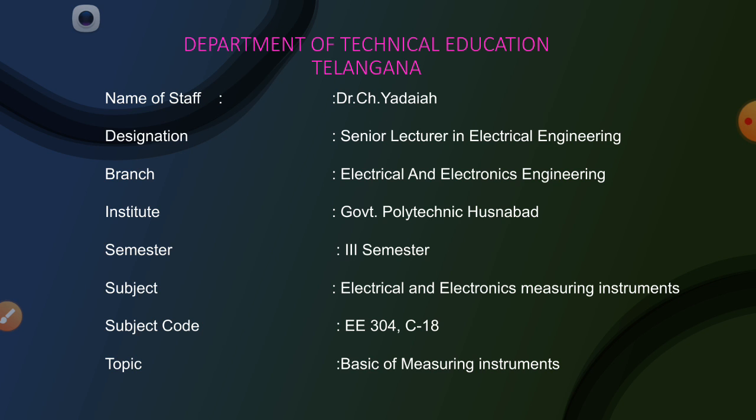This we have covered, and the secondary instruments are further classified into indicating instruments, recording instruments and integrating instruments. What do you mean by indicating instruments? They indicate the magnitude of an electrical quantity to be measured on a calibrated scale. Good examples are voltmeters, ammeters and meggers. They indicate at that instant, as we already explained with the speedometer.